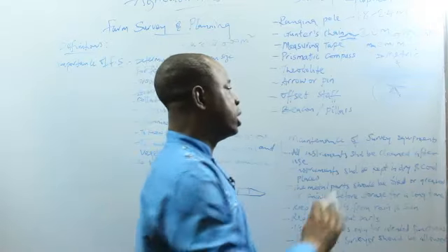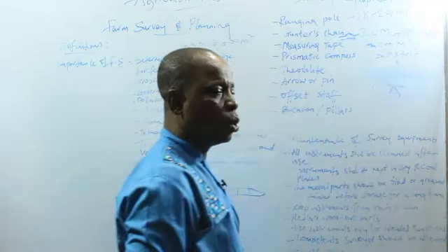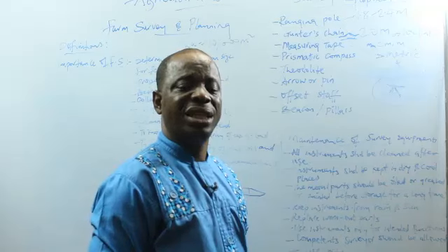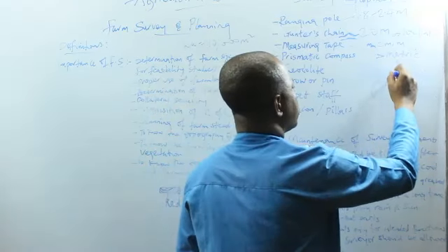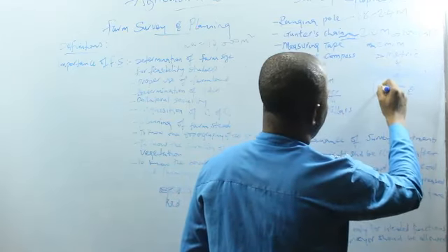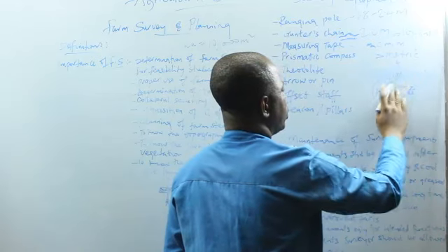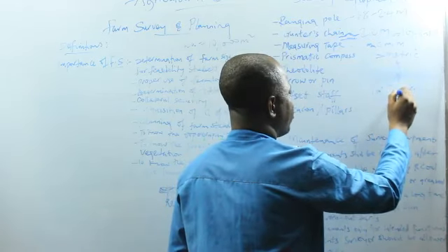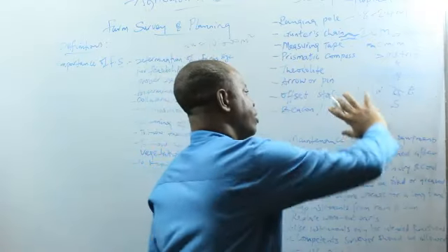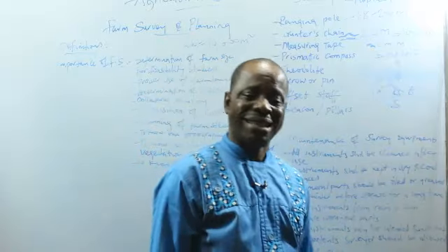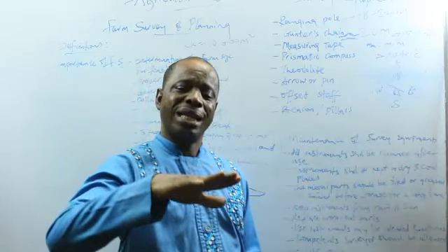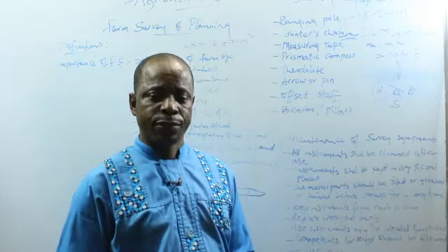And the whole thing is now covered with a prism. That circular plate is graduated to read in degrees and minutes. That means here will be north, here will be south, here will be east, and here will be west. It has a pivot at center, and a sensitive needle, and everything is covered with a prism. Prism is like a glass, so you can see through. This prismatic compass is now put on a tripod stand so that you can be able to read it. How is it used?